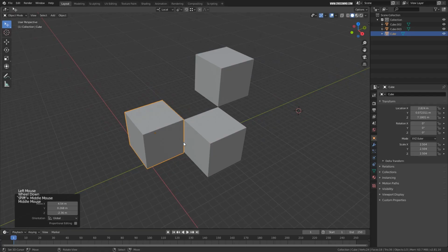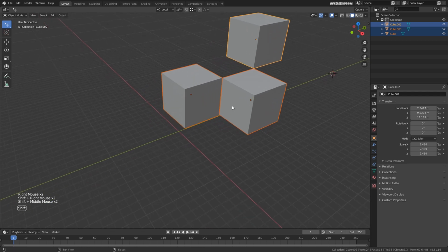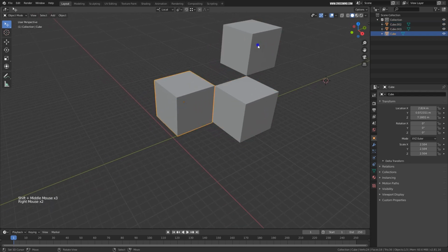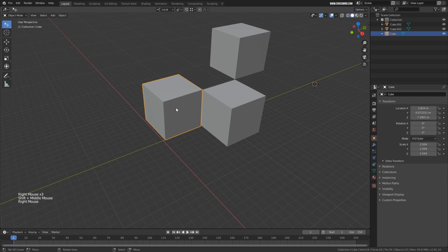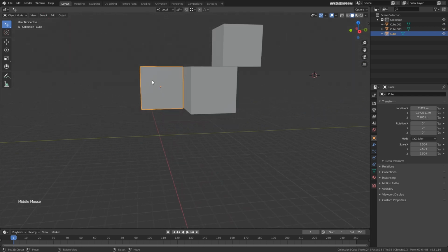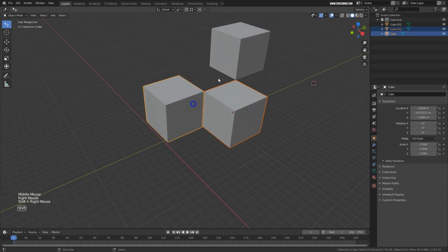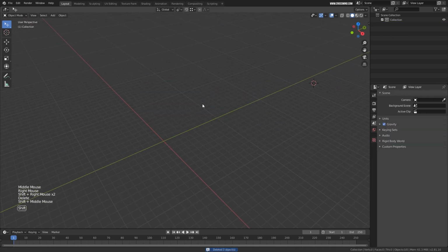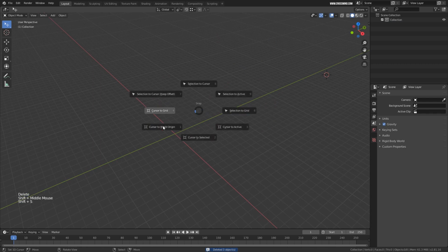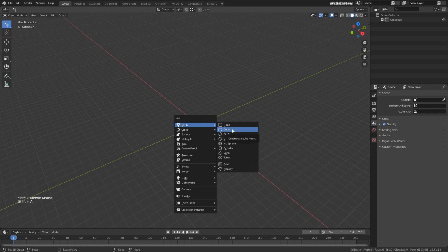All right, so one more thing I wanted to discuss before we start exploring more options. Each of the objects you see in the viewport has this yellow dot in the center. This is called the object origin. It's also known as a pivot point in other software. To explain this, I'll press Shift S and cursor to world origin, so that the cursor is in the center.